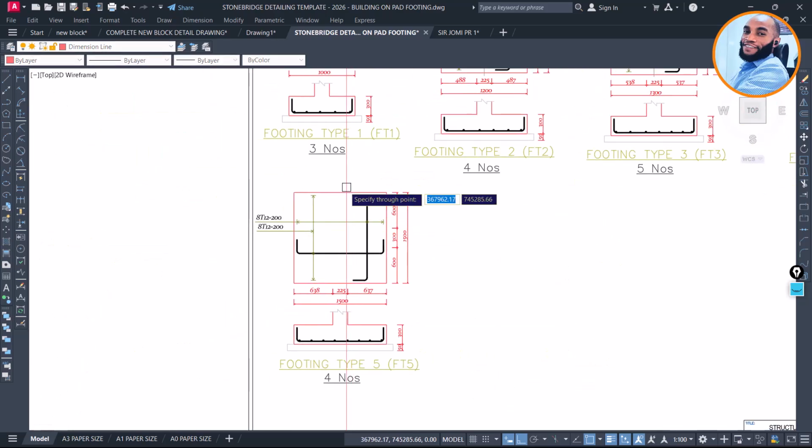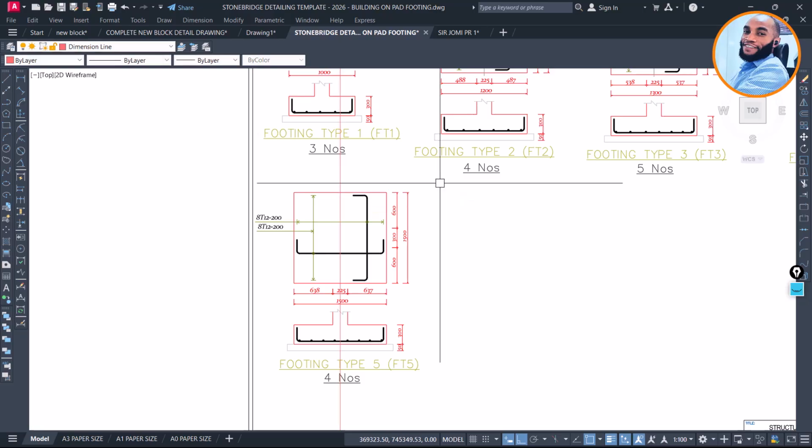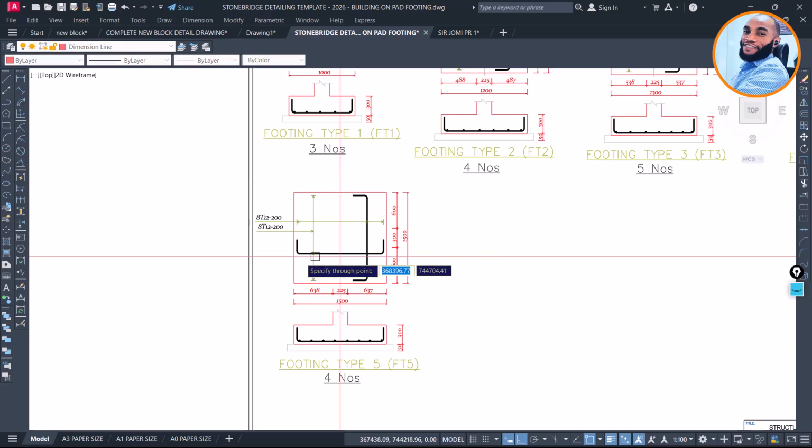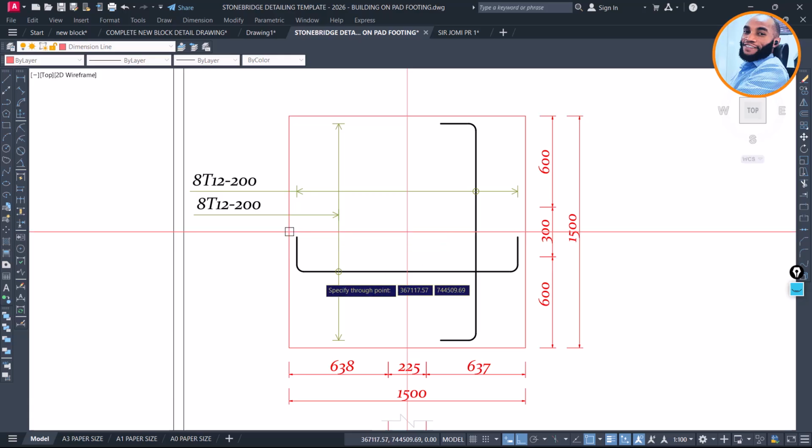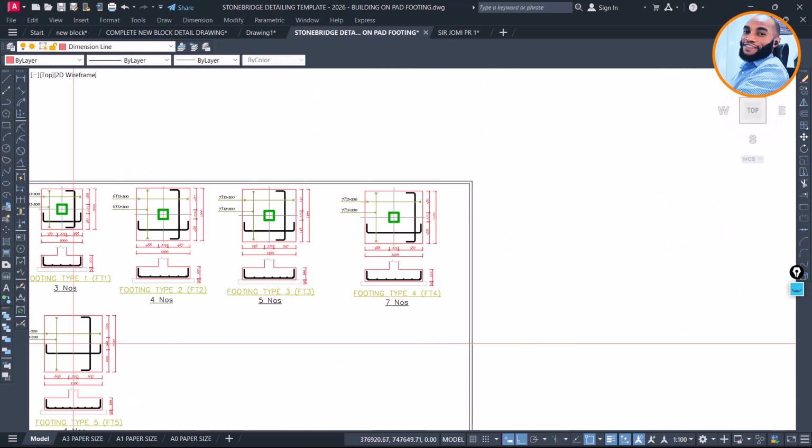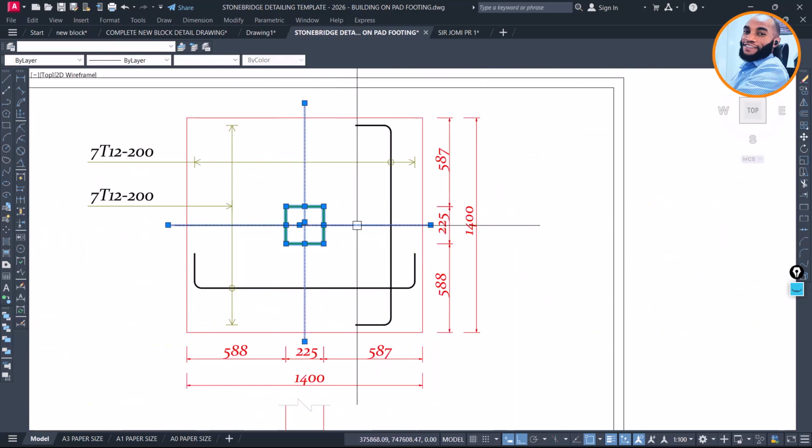Come here, look at the middle here. Keep this. Again, XL, enter, H, enter. Come here, look at the middle, exactly the middle. Keep this. Then copy this footing, the 60 square footing, and the grid lines. Copy them from the center point there.